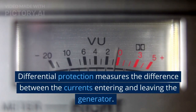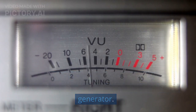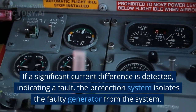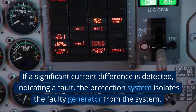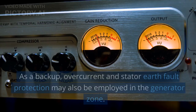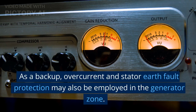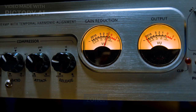Differential protection measures the difference between the currents entering and leaving the generator. If a significant current difference is detected, indicating a fault, the protection system isolates the faulty generator from the system. As a backup, overcurrent and stator earth fault protection may also be employed in the generator zone.